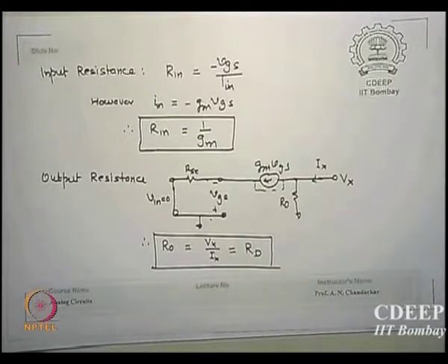Is that clear? What did we do by common gate? The gain is like a normal amplifier, its input resistance is relatively high and its output resistance is now controllable by me. How much RD I fix, that's my R0. Okay, that's exactly what it is, and it is in phase and therefore no problems of connectivity. Is that correct? Circuit can be connected directly from left to right. Okay, that's the biggest advantage common gate gives.